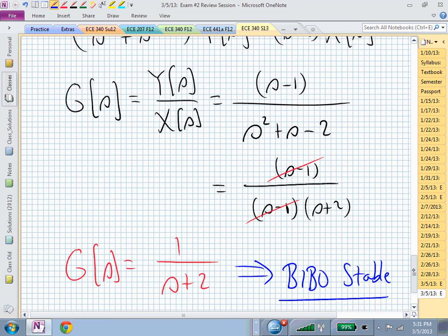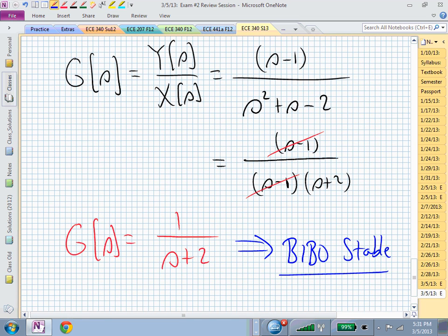It's usually done the other way. Usually, except the one example that the textbook gave you where they had an improper transfer function. Usually, if you have an asymptotically stable system, then you have a BIBO stable system. Usually, that's the implied direction. So if you look at your characteristic polynomial and you find all of its roots are in the left half plane, you can be assured that your input-output stability will be guaranteed if you have a strictly proper transfer function, which means the numerator polynomial is strictly less than the denominator polynomial in order.